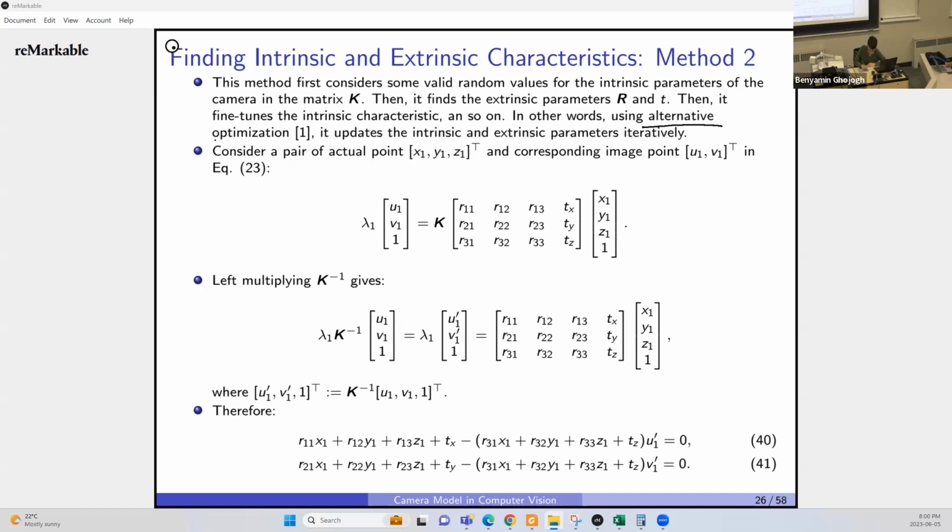I have a question. Yeah. So for the mapping, are they even given, or do you find them using camera calibration? You can find them using camera calibration. Why? Because mapping is not just only intrinsic. For intrinsic, maybe they can be given by the factory, but extrinsic, it depends on where you put your camera. So is this where? Yes, exactly. The checkerboard that they use for the camera calibration is exactly for finding those 6 points.